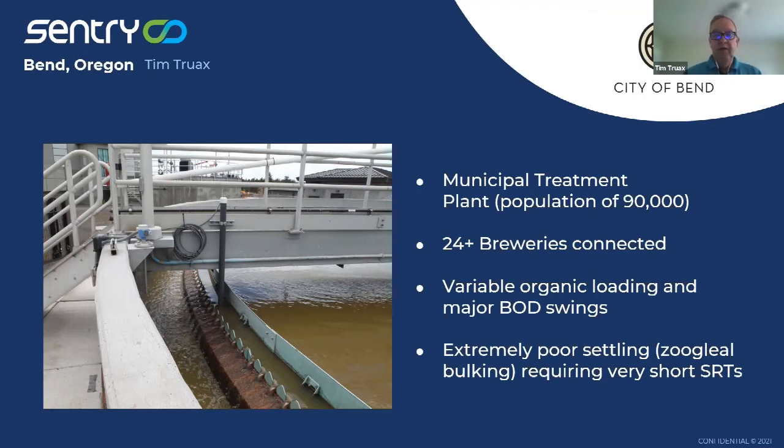The city has an industrial pretreatment program and staff that would sample the breweries, but because of the batch nature of brewing operations, we felt that we were missing a lot of the slug loadings that were discharged into the sanitary sewer system.